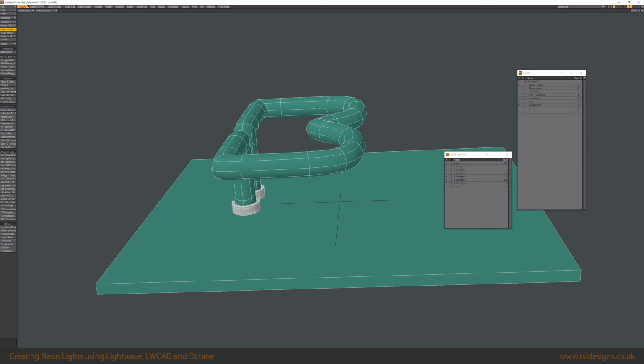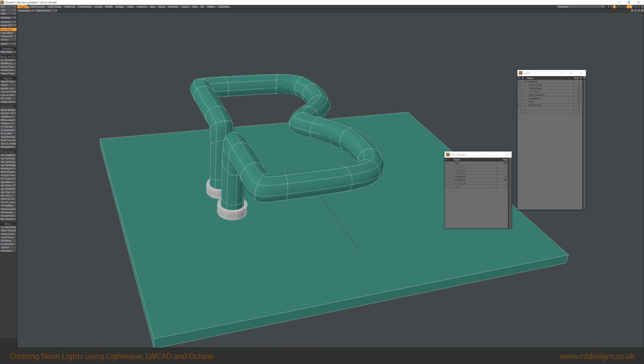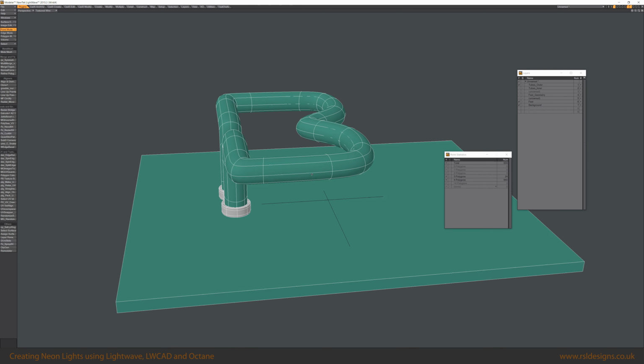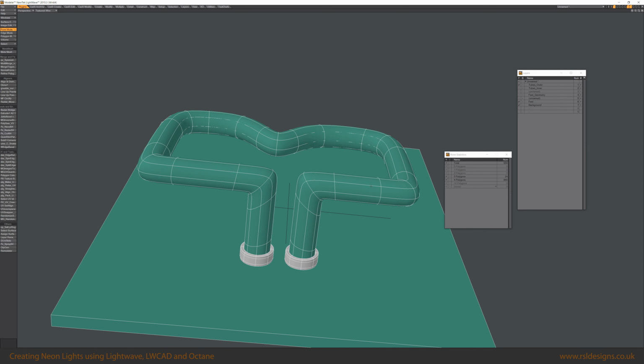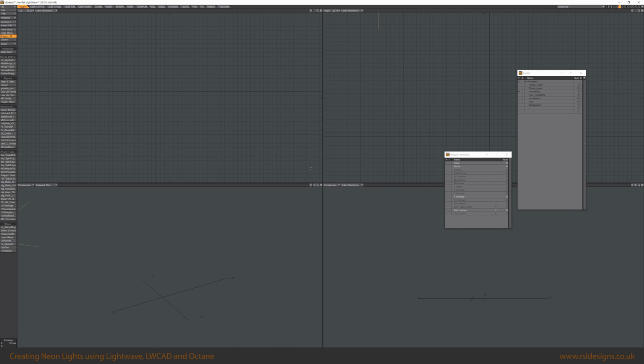So to create the support arms for longer parts of neon tubes that you saw in the final render, we need to take a part of the geometry of the neon tube, the outer casing part, and use that as the base to build the first support part, the metal ring that goes around the outer tube.